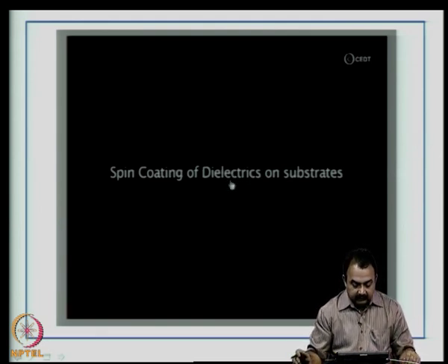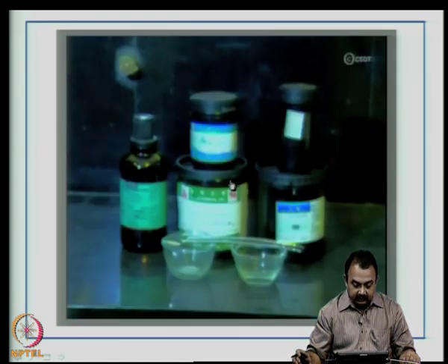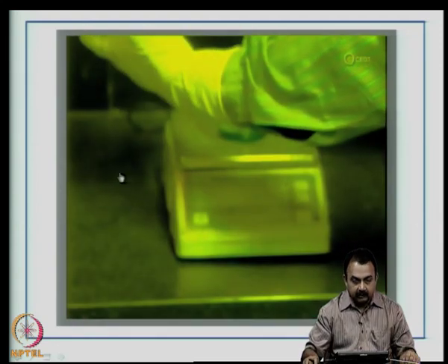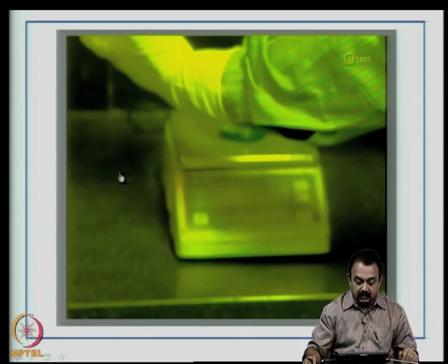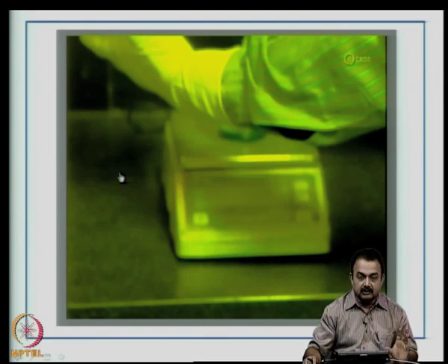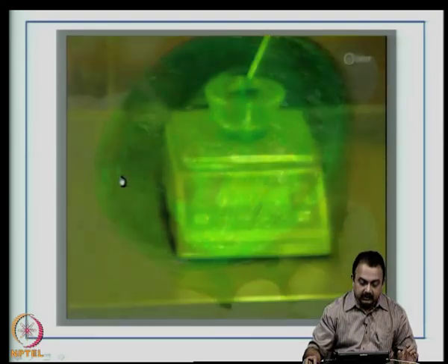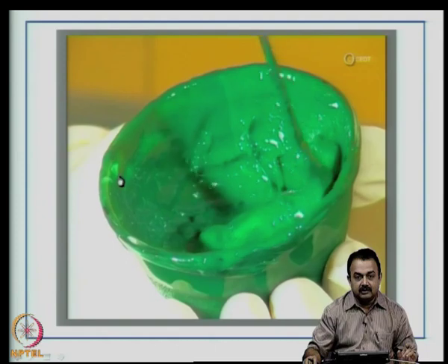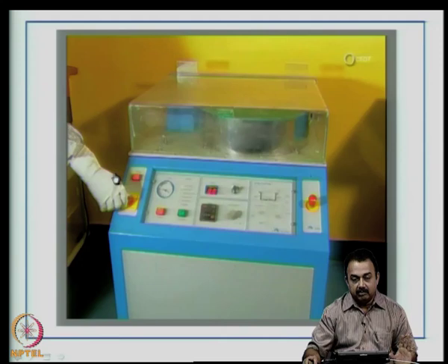In this video, we are going to explain spin coating of a photoimageable dielectric on an organic substrate. Here you can see basically dielectric is selected, which is photoimageable. Typically, we want about 30 to 50 microns thickness of the dielectric for imaging. Now, in this particular case of a demonstration, there are two materials A and B, which are weighed separately and now they are mixed. So, the proportion by weight of the different materials, including the solvent, is very important.